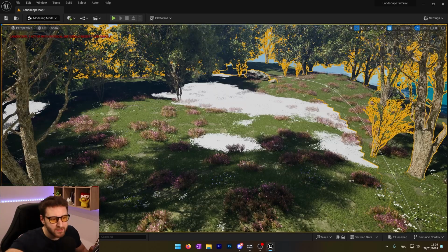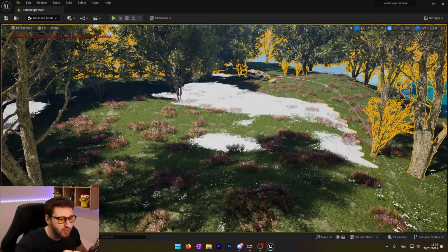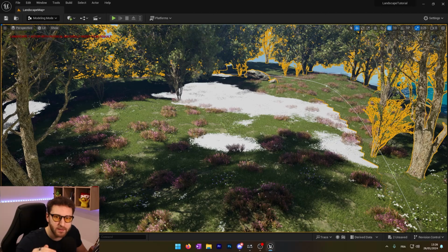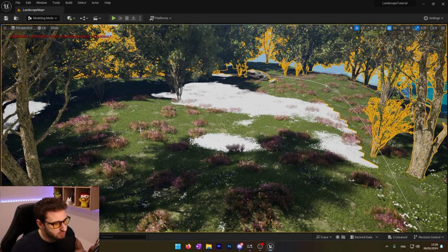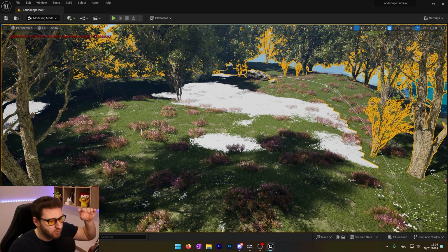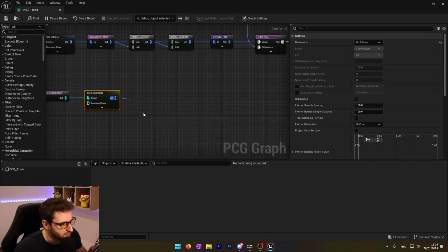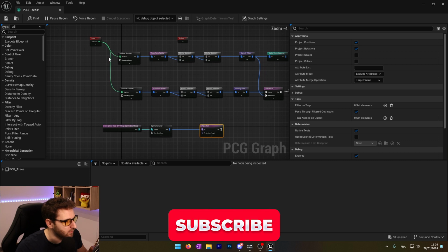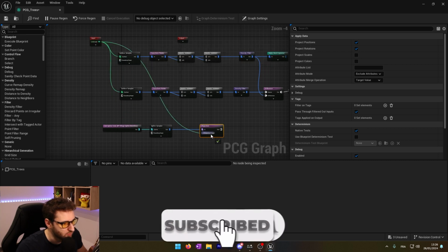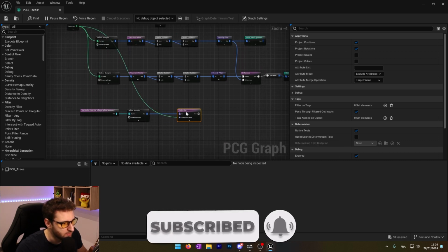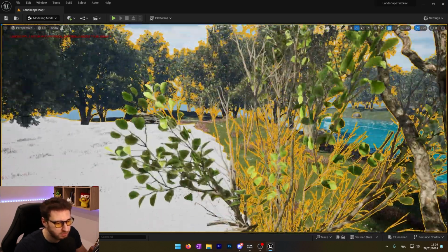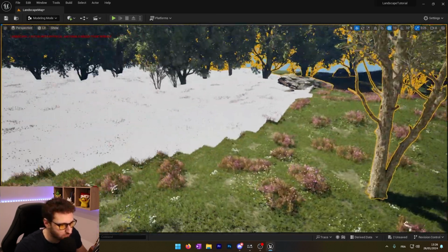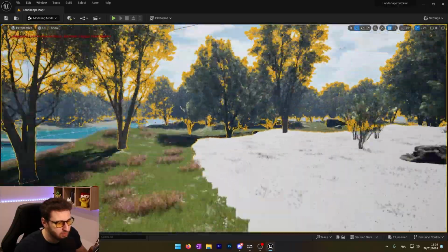in our spline. As our landscape has some little hills, we will need to project our boxes onto the landscape to be sure that, you can see in here we don't have any box, we cannot see them because the landscape is higher than the box. So we'll do projection. And the projection target will be our landscape. So we can drag this landscape, put it there. And if I check projection in the debug, we can see that we have the boxes on the landscape.